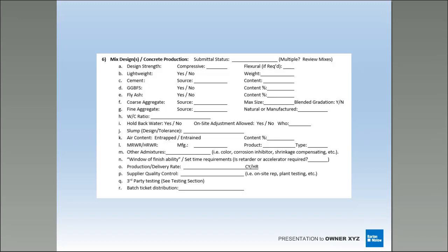where it's going to help you is, say you're in a project and the place and finish guy is going to be there the first 3 months, and you're not coming in until walls are up, studs are up, and you're going to polish this thing 6 months later. Well, if the break history shows that mix is coming in on a 7-day break at 4,000 to 4,500 psi, but in 28 days I'm hitting 7,000 psi, that's going to change your cut factor. For all intents and purposes, it could change your price, because you could be pricing this job to cut a 5,000 psi mix, and you're breaking at 7. It's going to be a lot harder to cut.